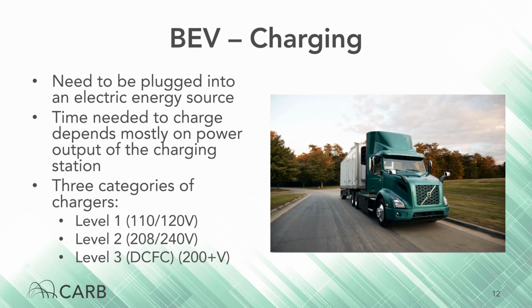Charging rates are faster at the beginning of the charge compared to when the battery gets closer to 100% capacity. Therefore, many BEV operators may choose to stop charging at 80% or 90% instead of a full 100% charge to spend their time more efficiently. It is also optimal for long-term battery life that the charge stays at or under 80%.